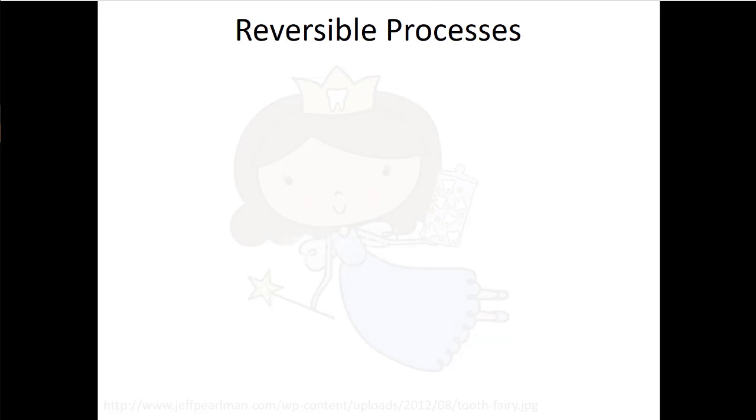But just because something doesn't exist doesn't mean that it's not useful. Oftentimes, for us as engineers, it makes sense to talk about an ideal process, or a reversible process, a process without any friction, because this is the limit of what's possible. We can't actually get to a case where that pendulum comes all the way back up, but we can get close. If we keep making better and better bearings, then we'll get closer and closer to this frictionless state. We can never quite get there, but that doesn't mean we shouldn't try,